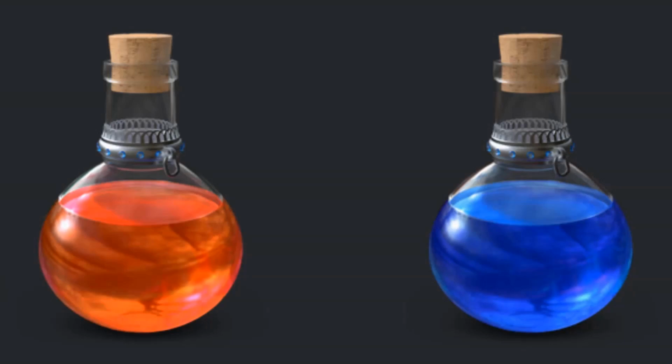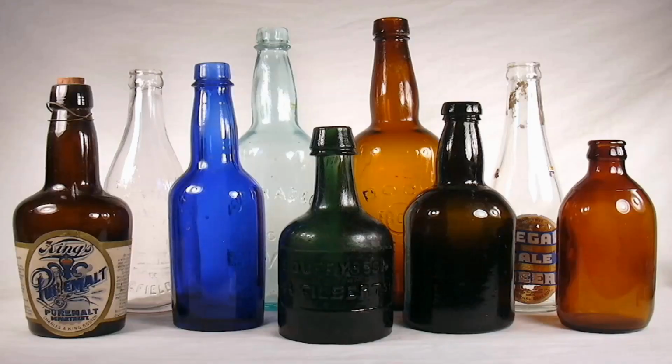How do we create these bottles? We can clearly see that the extrude option cannot be used. If we observe carefully, all these bottles are round and have an axis. When we spin about the axis, the front view and the side views always remain the same.